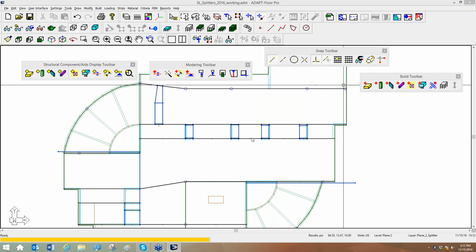If you just went in and drew arbitrarily a bunch of splitters, and then, let's say you assign them X direction, and then you drew some support lines in the X direction, the program would interpret those X direction splitters when it's generating tributaries for your X direction support lines. But the X direction splitters would have absolutely nothing to do with the generation of the Y direction support lines. They are used in conjunction with the support line, but the directionality of it is what makes them independent.